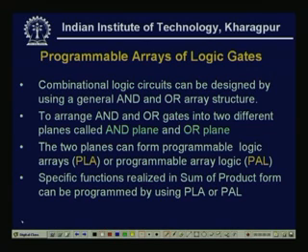We will see later what is PLA and what is PAL, but all are programmable arrays using AND planes and OR planes. Specific functions can be realized in sum of product form, and they can be programmed by using PLA or PAL.